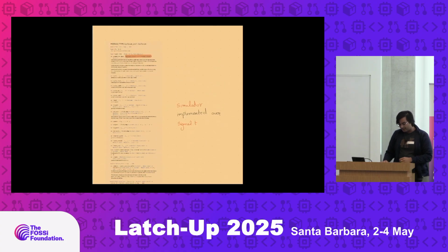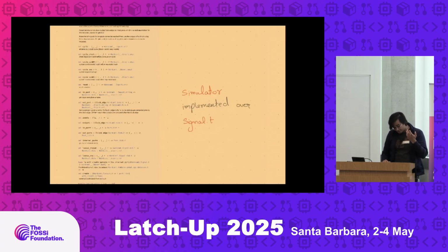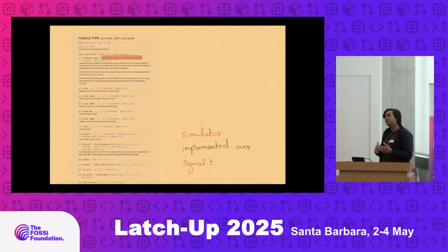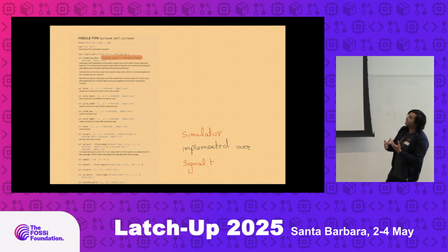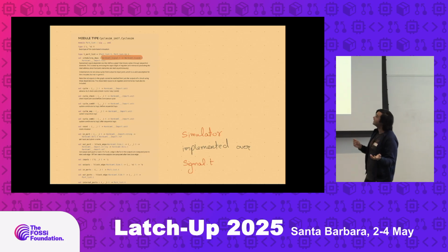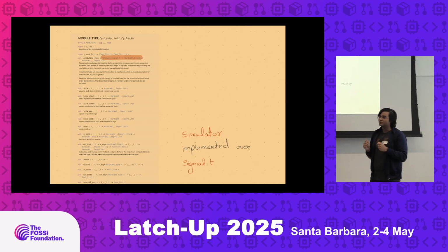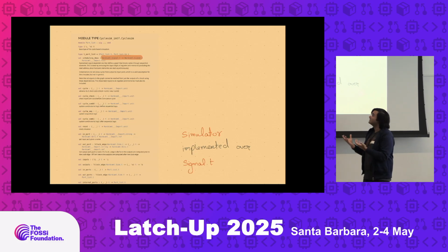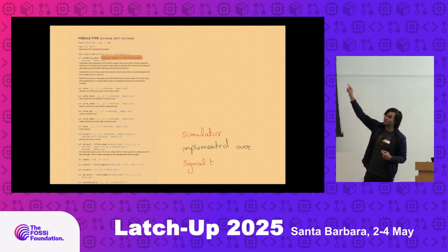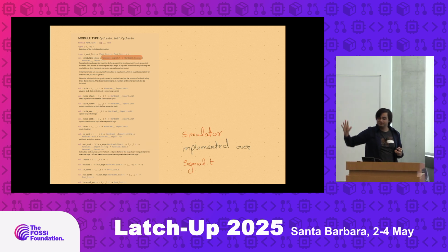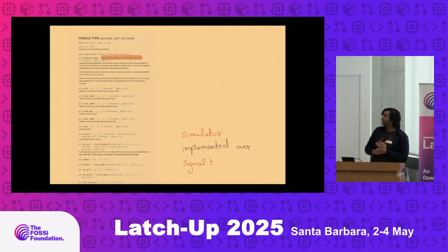And in addition to that, there's a simulator implemented in Hardcaml, again, using the kind of idea I've described to you. And there's actually several simulators. If you want really quick simulations for unit testing, we use something called CycleSim, which can run inline, but is written in OCaml and is slow for big designs. But we also have CycleSim_Verilator, which will compile your design, again, by compiling those 6 primitives I showed you at the top, roughly speaking, to get verilated components that you can simulate.